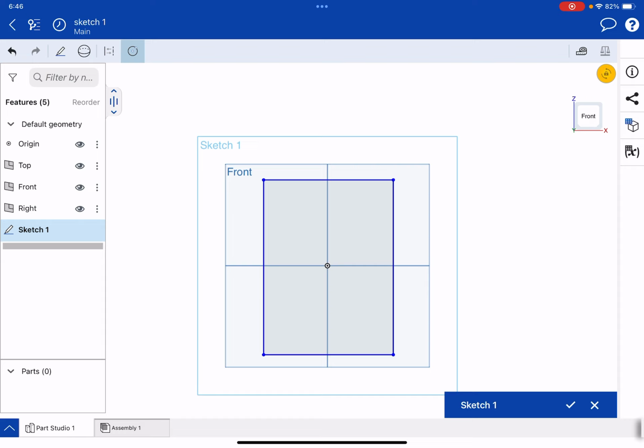One of the properties of Onshape is that it allows you to snap onto specific points, critical points. A critical point can be a midpoint, an endpoint, a spot on a line that's perpendicular to another line, etc. So automatically it will snap you onto those points. If you don't want to snap onto those points, then you have to do a little more work, either zoom in, zoom out. Since we're working on an iPad, that's what we would have to do.